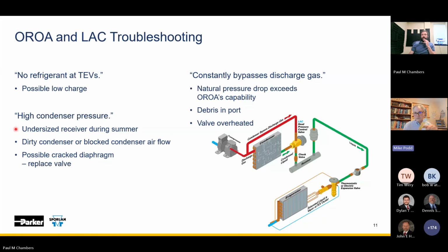And then our valves do have diaphragms in them. So just a key thing, with one of these valves, if you take this cap off to adjust it and you get pressure coming out of here, even if it just goes, that's an indication that the bellows have been compromised. So that valve should be replaced, right? If it's just a little something, maybe due to ambient conditions, but don't leave the cap off, put it back on, because you don't know how close those bellows are to completely rupturing, and then head to the supply house and get a replacement.